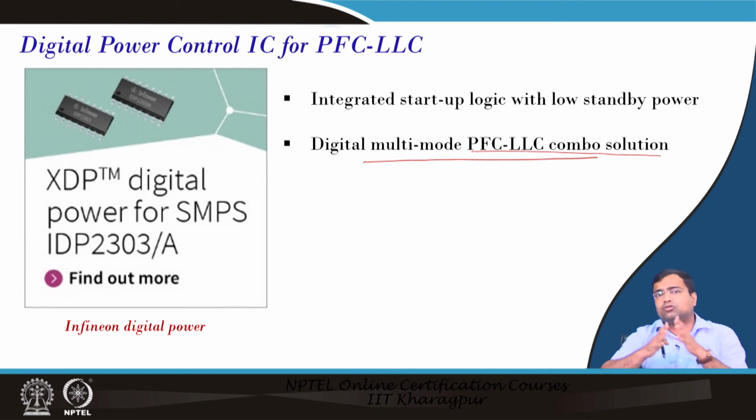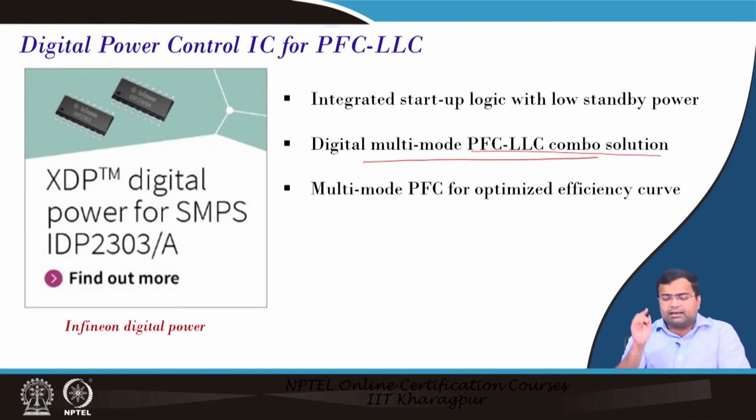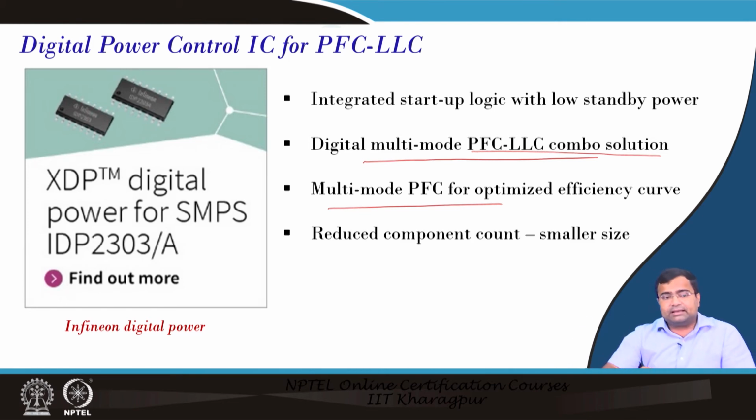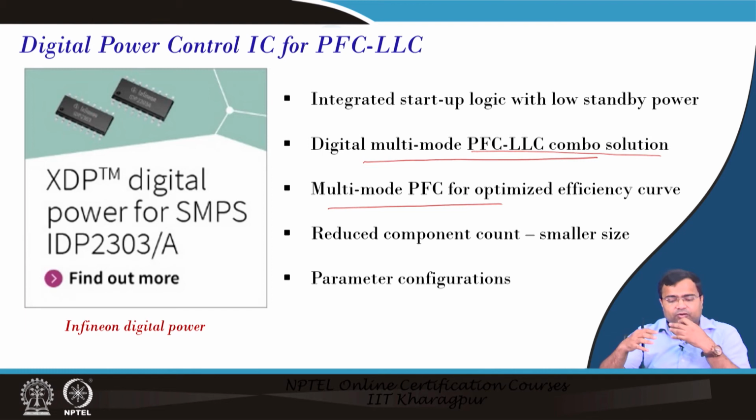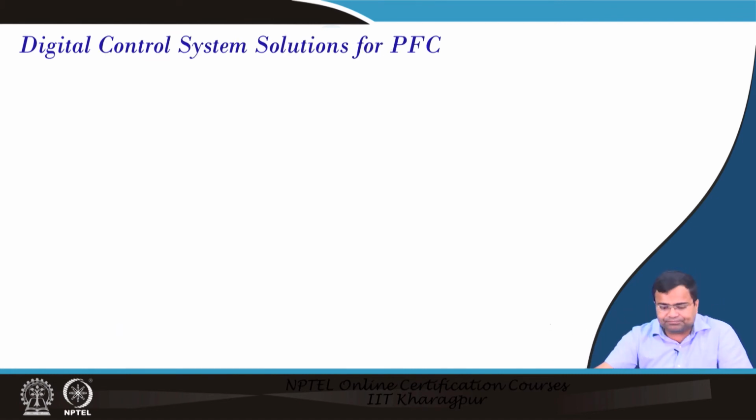This multi-mode control enables to achieve high efficiency over a wide load current range, and in this course we will demonstrate multi-mode control along with the hardware case study using FPGA implementation. And multi-mode PFC can optimize efficiency for a wide range of load current. Then because of digital control, everything is inside the IC, so it reduces component count, so smaller size, and the parameters can be configured by means of hardware, software and firmware integration. So, that means you can tune the parameters from outside.